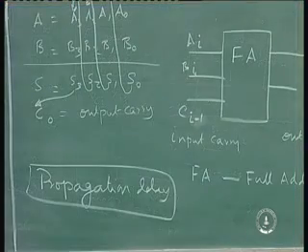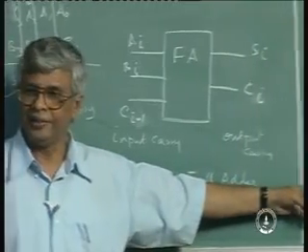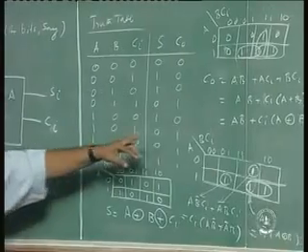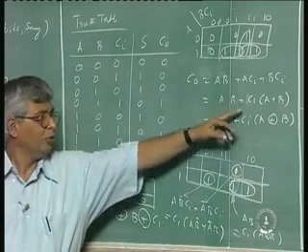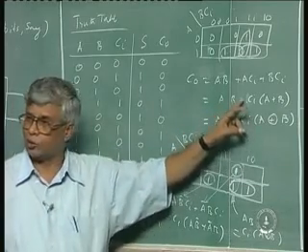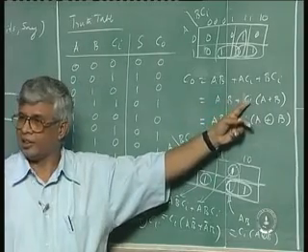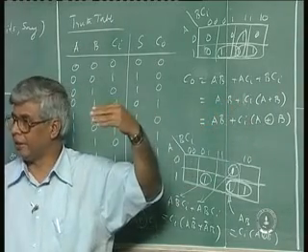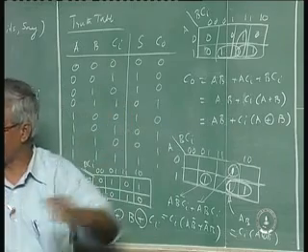There is only one exclusive OR gate and one AND gate. When you go to a full adder, there are two exclusive OR gates and a two-level gate, one AND gate feeding into an OR gate. Whether you use this model, let us use this model, one OR gate, one AND gate feeding into another gate. So there is going to be some delay there. So there is going to be delay in these two stages of gating.